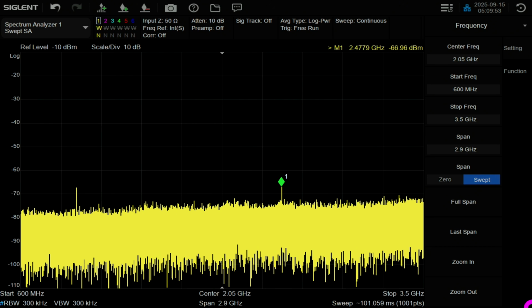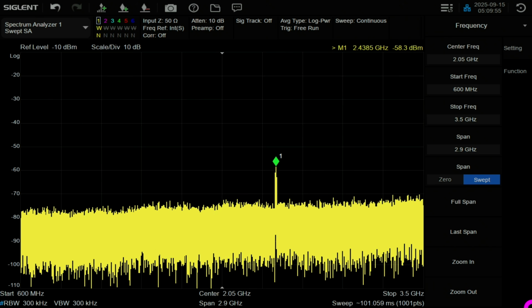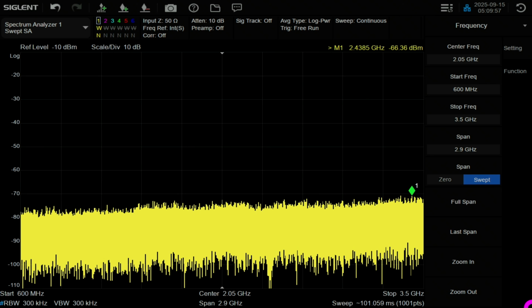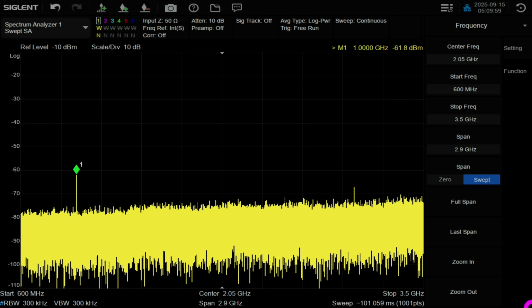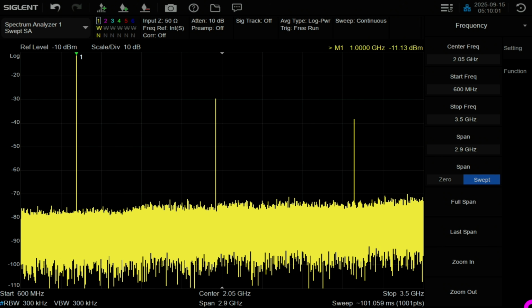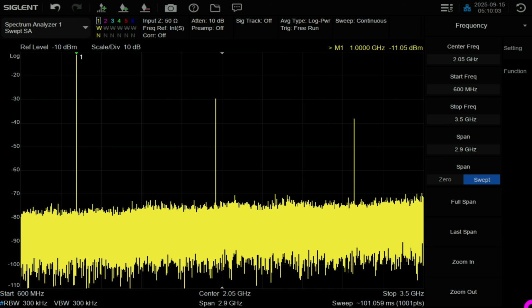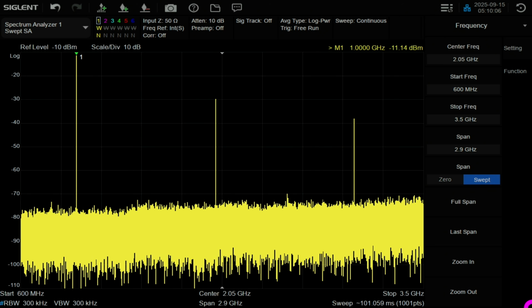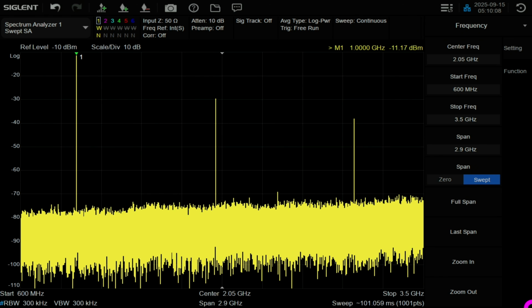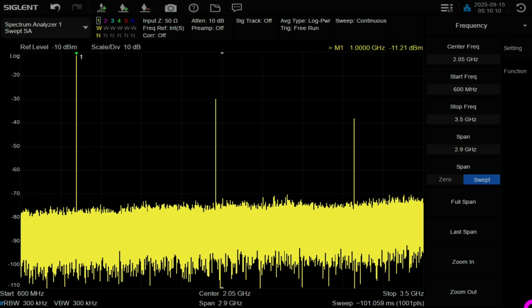All right, so first thing first, is the VCO output really at 1 gigahertz? So let me go ahead and probe directly the output of the VCO. Here's the output of the VCO, and check it out. It is exactly at 1 gigahertz. Now it's going to have a little bit of harmonics in it. That's normal because the VCO is putting out quite a bit of power. And yeah, indeed, we have exactly what we expect.